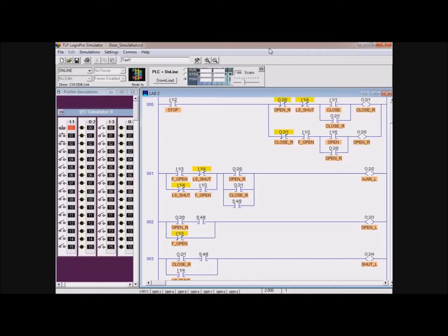So what we do is write programs in what we call a high-level language, and this is the same language we would use in electrical control. Then we run it through a special program called a compiler, which literally converts this to binary and uploads the binary program into the computer. So what high-level languages do is allow us to write programs in a language that's unique to the trade, and then let the compiler make the machine language program for you. So I'm going to download this, and you'll have to do the same thing, even though this is simulated, and then we'll have to switch the PLC to the run mode.